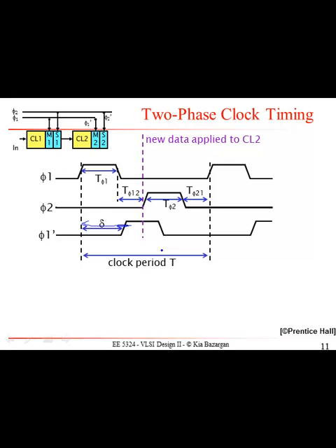That's the phase distance between them, and that could potentially be a parameter that you as a designer could control, right? You have the logic that generates phi1, phi2. You can decide what T phi1 wants to be. You can decide what T phi12 wants to be, and by moving these pulses around, you can have more flexibility and fix stuff potentially.